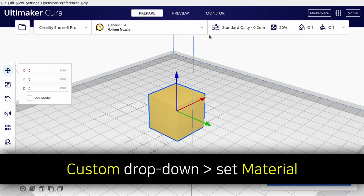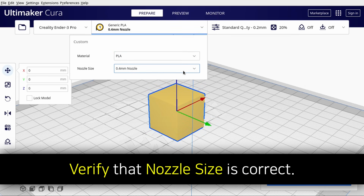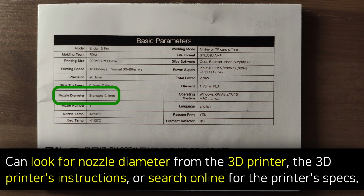Next to the drop-down with the name of our printer, we have the Custom drop-down. From here we can set the material so it matches the material of the filament we are using. For my example, I am using PLA plastic, so I'm going to leave the material set to PLA. After that, we can verify that the nozzle size matches the diameter of the nozzle in millimeters for the printer that we are using. Some places where we can try to find the nozzle diameter of the printer we are using are by looking at the instructions or the box the printer came with. We can also look at the printer itself, or we can search online for the specs of our printer.